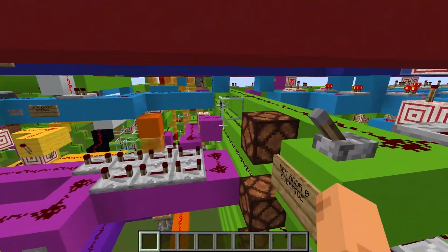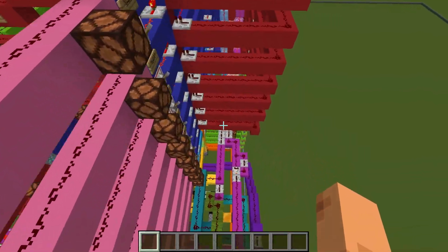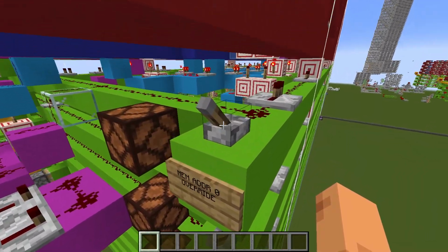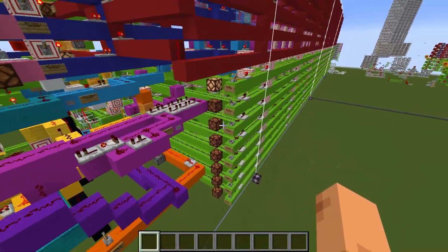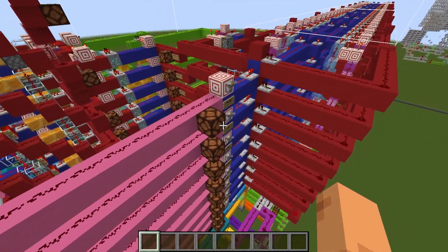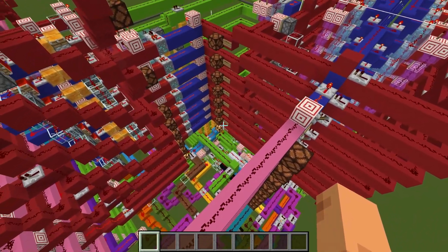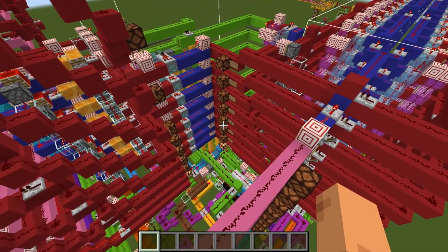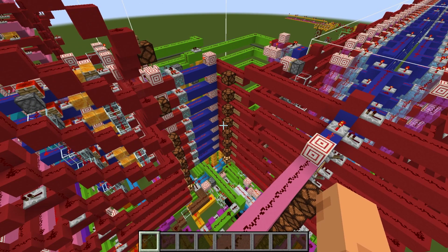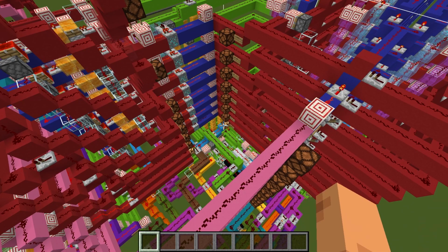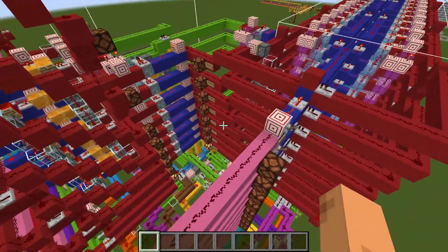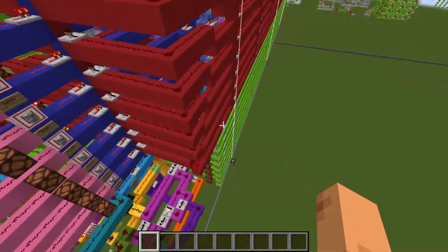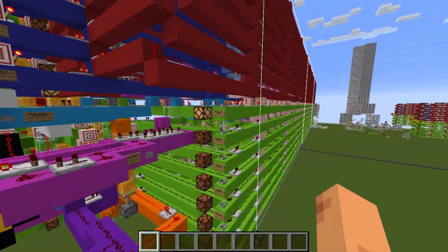We saw that the first byte was 8. Then we can look at the second byte by flipping this to get memory address 1, where we have value 1. So far memory address 0 is 8, and memory address 1 is 1. That gives us our first full complete instruction, and we can get back to that, but that's something to keep in mind.